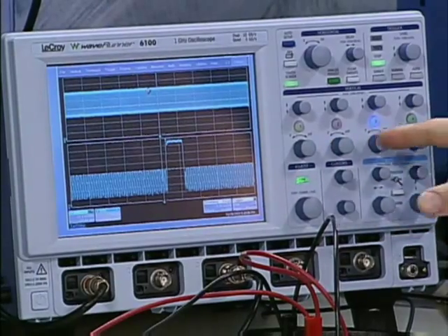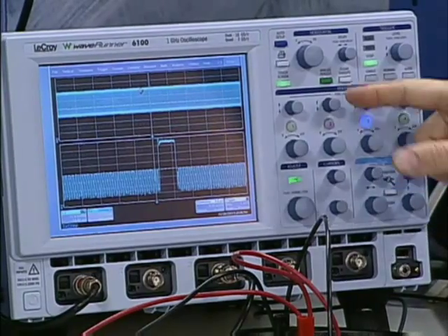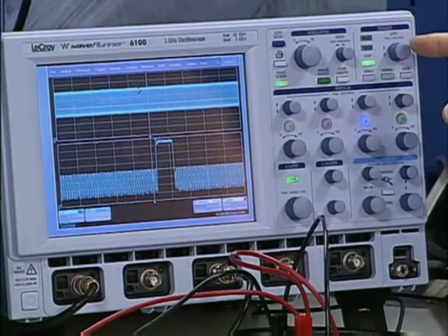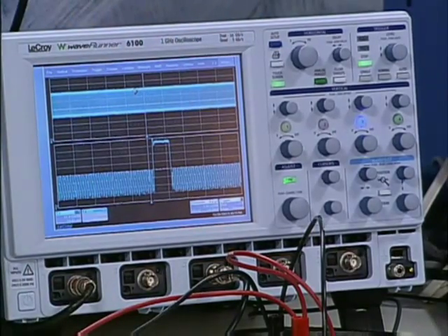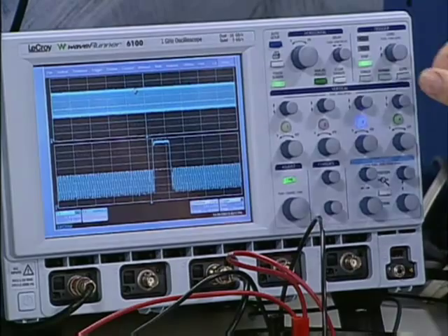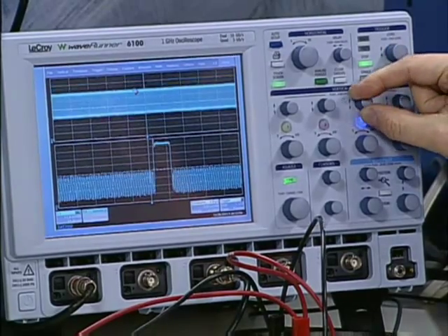So good. If you look at this, you can see there's one voltage knob per channel, there's an offset knob per channel. Here's your time base, your horizontal knob. Here's your trigger level, nice knob. No menus to get to those things. You just turn them and they're there. That's wonderful. So in fact, if you change the offset here, you can move it up and down.